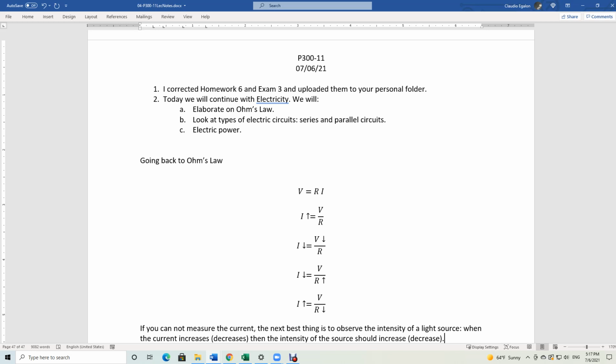So just go ahead and gauge how much the intensity is with your own eyes. It's going to be a qualitative perception, of course. I'm going to look at that too. And then I'm going to get a resistor, 270 ohms in this case, and connect it to this circuit, and hopefully we are going to see a change in the intensity compared to the other situation.